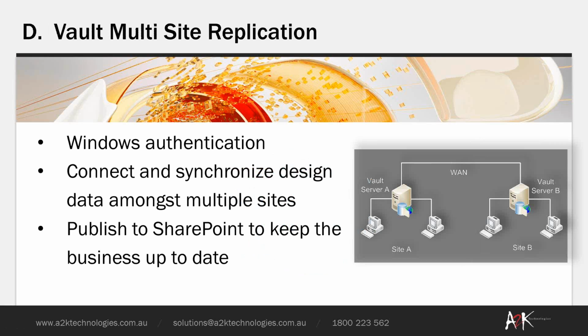With multi-site replication and Autodesk Vault Professional, you can set up Windows authentication. So you can link to a group in Active Directory, and you can make it easy for everyone to log into their Vault. And you can also synchronize your passwords with your active domain in Windows using Windows authentication.